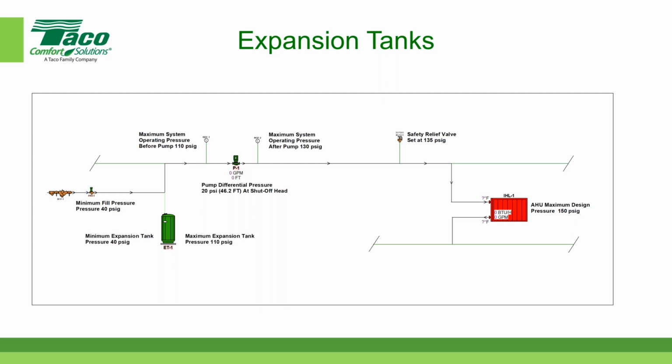So you have to take the volume of all of the piping system and all the equipment, anything that adds volume in terms of water to the system, add that up, add a safety factor, and that becomes your system volume. Now you can do that either manually or there are very sophisticated software packages out there.